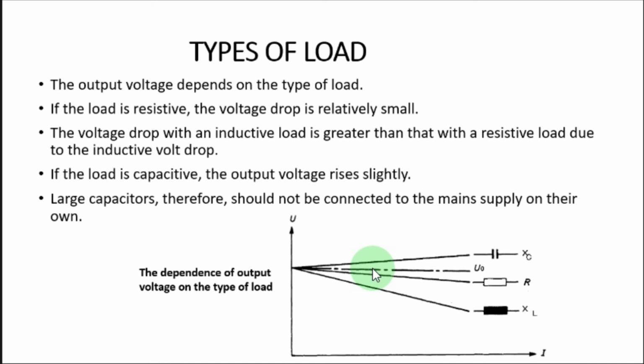And also we said that we can calculate to get the maximum efficiency. We found that the core loss and copper loss should be equal. So to get the maximum efficiency, you can find the other parameters like the load current, the load power factor, or the winding resistances, core losses, etc.